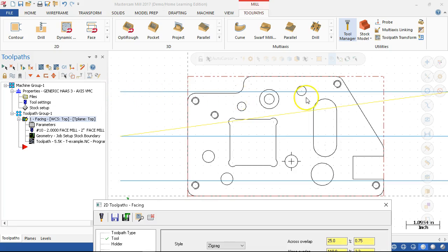So we're looking at the approach, since this is coming out on the one way was our previous, coming across, lifting up, coming back. This distance is our approach, and how much it is, basically our 3-inch cutter overhanging the part at that 25%. That's what we're seeing as where it's determining where this first one starts and this last one ends.